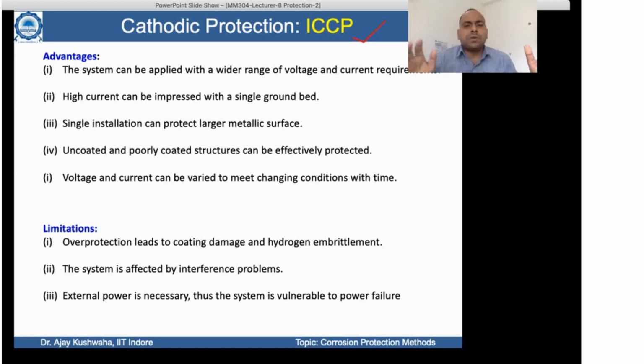So I will just revise here. Cathodic protection means we are going to protect the anode by creating a cathode, creating a cell within the system so that local cell formation should not be there in the metal. Otherwise, what will happen? The metal will form an anode somewhere and a cathode at some other position, and local cell formation will initiate the corrosion. But if by some means we are creating an artificial cell where another cathode is there, the anode is going to be protected. If that cathode is directly connected, then it's not a kind of cell, and we call it just a sacrificial anode.